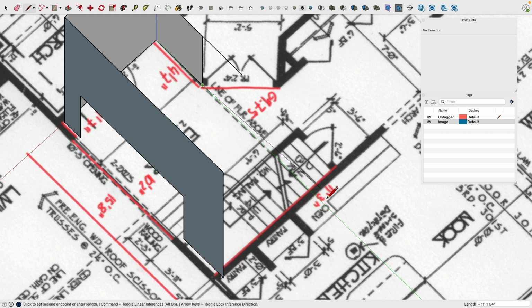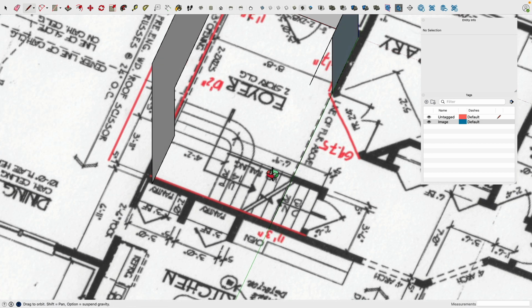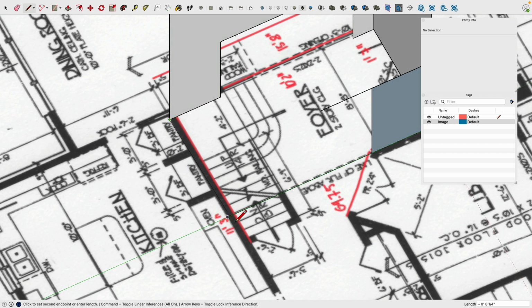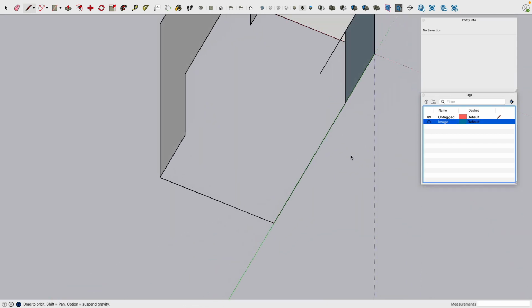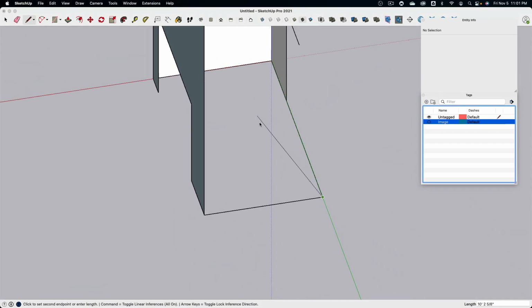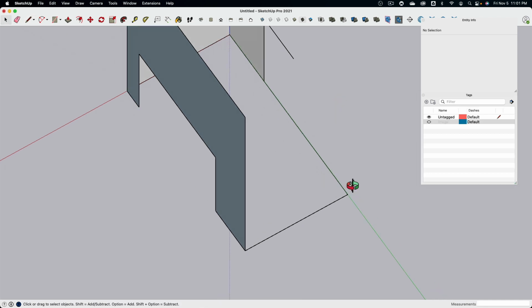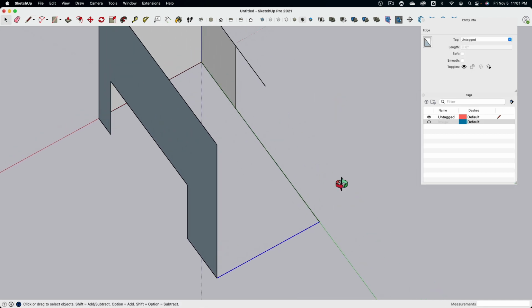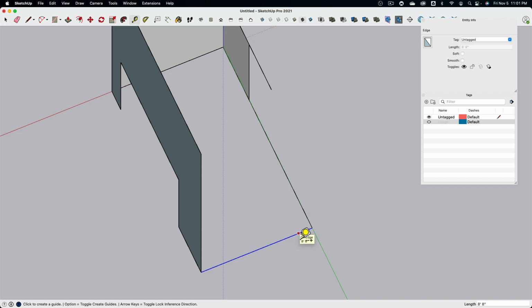I will extend a line, you see, along the y-axis. There. Cool. The reason why I extended this line is I can now connect this a little bit. There we are. And let me turn this off. Okay, good. So from this line, offset 3 feet 11 inches. No, wrong direction. 3 feet 11 inches. There. This is where actually this one line has to be.